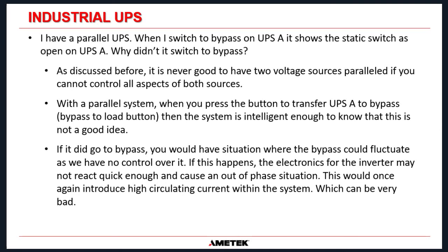So as discussed before, it is never good to have two voltage sources paralleled if you cannot control all aspects of both sources. When you have a parallel system, remember, both inverters are looking at each other and they're perfectly synchronized together. They're looking at the power factor, active power, reactive power, and all that good stuff. So they're completely in control of each other and they share the load perfectly.